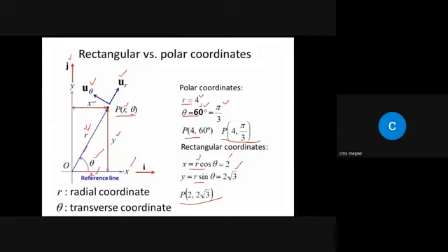You can make the same diagram with the help of the Cartesian coordinate system. For example, if you want to draw this line, it is very easy to draw this line by using Cartesian coordinates. Then if you want to draw this line and again this line, if you are given this angle and this dimension, from here till this point, it is very easy to draw with Cartesian coordinates. Then from here till this point, you can do it by using Cartesian coordinates, but the easiest way is by using polar coordinates. If this angle is 30, you just take r equal to 2 and angle equal to 30, and you will get this point.